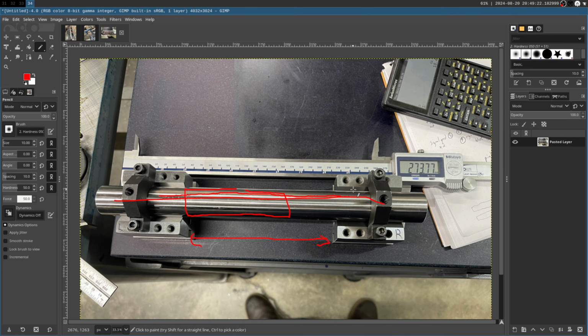So that means that basically there's 1 or 2 micron of error in this setup in being parallel to the surface below it. And that's all I care about, because I am setting my level on top of this round bar. And thus, what I'm trying to do is transfer information about the contact, the rectangular contact patch underneath this block and underneath this block.